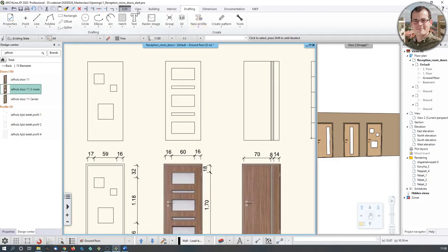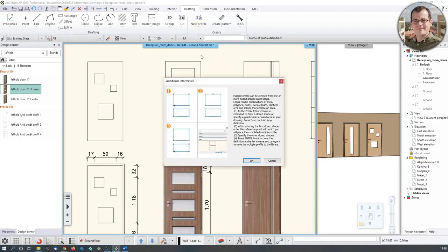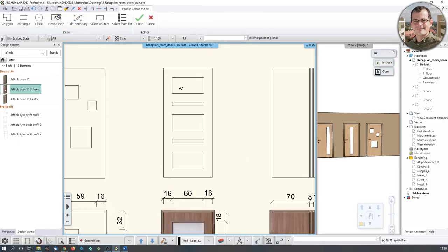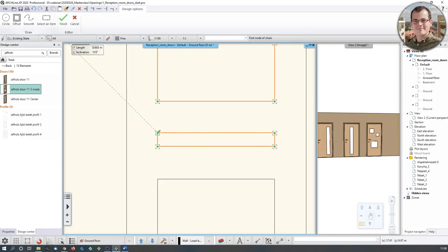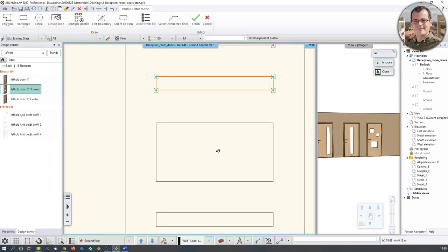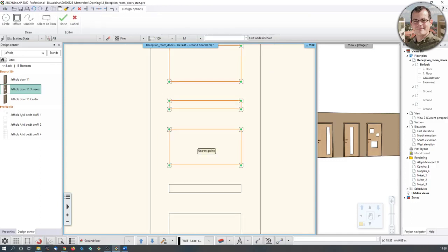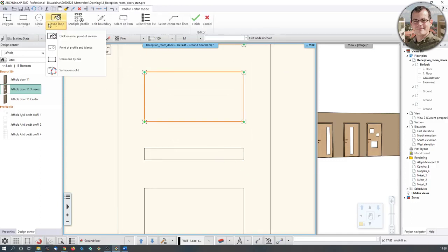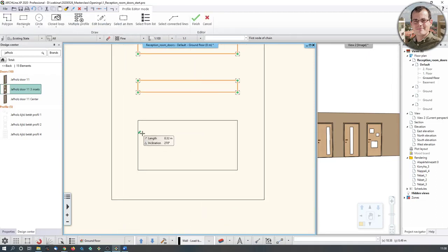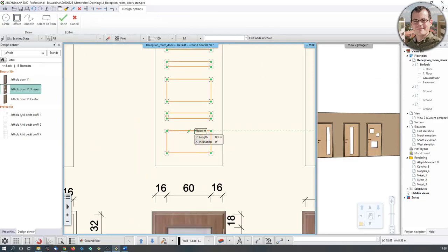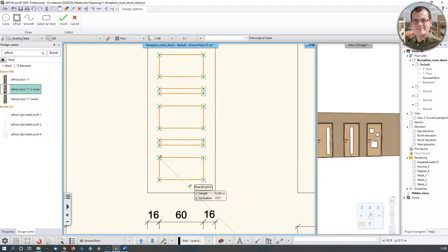We just go to the group definition, we define multiple groups, and in this case it's going to be 5 of them. So again, clicking on the element, clicking on the paint bucket, defining the insertion points. Again, this you have to do 5 times, but I could be using what I have already saved into my library, but I want to show you the whole story anyway, and that way I can illustrate that it is in fact very easy and fast to create a group like that. This is not limited to doors and windows, you can use this option to create any kind of multiple profiles, maybe for columns or wall definition. So this is the way to do it.